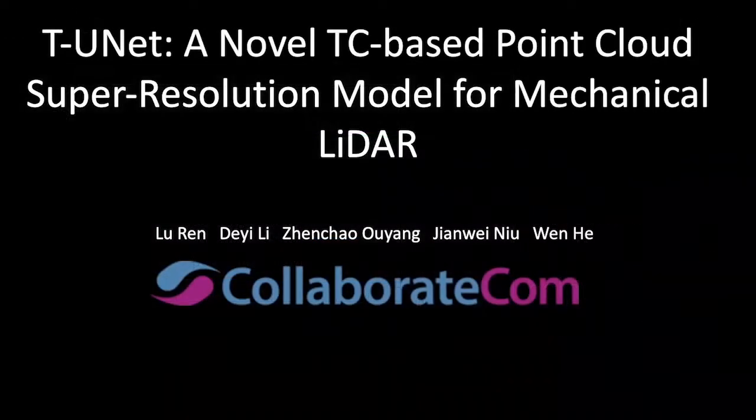Finally, I make a conclusion. Dense point clouds from high-cost LiDAR support stable perception for autonomous vehicles and robots. However, the high cost also severely restricts related applications. To achieve better perception performance based on sparse low-end LiDAR, we designed a novel T-UNet model for point cloud super-resolution. In the future, we will make several improvements.